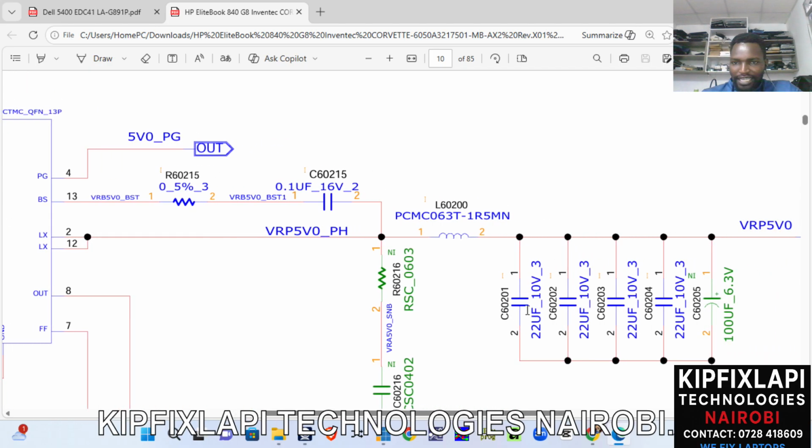Along that inductor, we have the filtering capacitors of different values, 22 microfarads. Can you see these capacitors are all the same? You have MLCC capacitors, these ones. But that one has a symbol of a different capacitor. You can see it is flat there, with polarities. So it means this is a chemical capacitor. So here, the final part, you have a chemical capacitor.